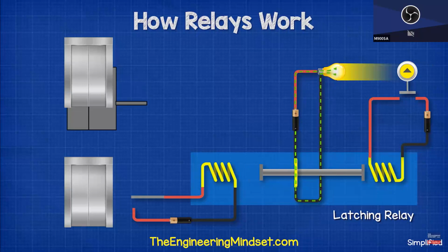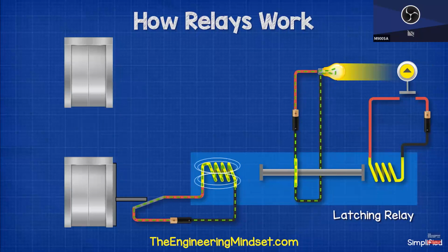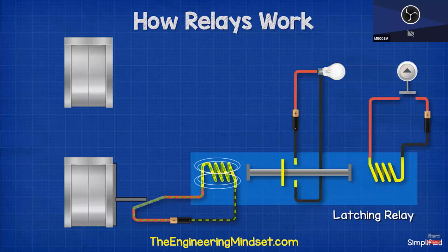Once the elevator car reaches the lower floor, it makes contact with the off switch. This powers the second electromagnet and pulls the piston away, cutting the power to the lamp. Latching relays therefore have the benefit of having positional memory. Once activated, they will remain in their last position without the need for any further input of current.